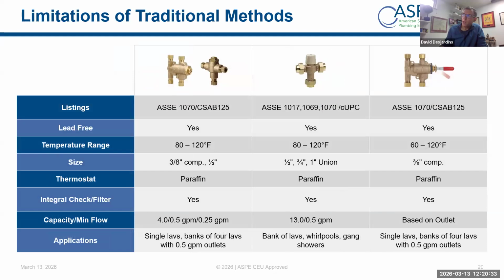For point-of-use mixing, ASSE 1070 mixing valves, this is very standard in the industry. These are a 4-port valve, H pattern. So you have your hot and cold coming in. It's very compact. You have the mix coming out and then the cold going straight through. If they have the sensor faucet, you can cap that. You have a 3-port valve.